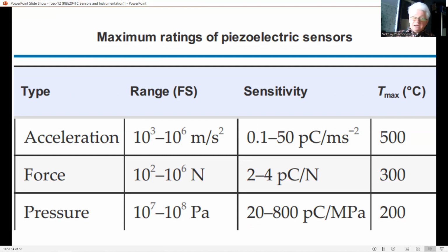When applying piezoelectric sensors, the following points should be considered. First of all, material properties depend on the electric loading, open or closed electrical terminal, and hence all sensor properties like sensitivity and resonance frequency omega depend on the load too.